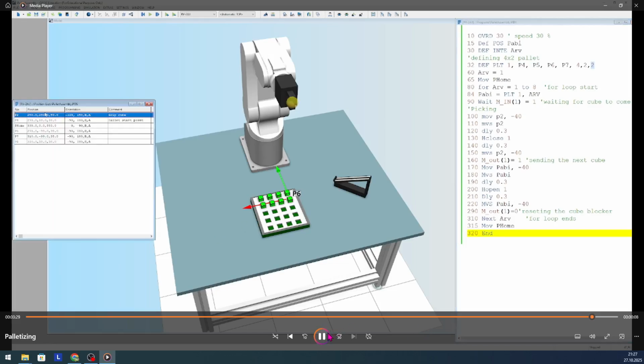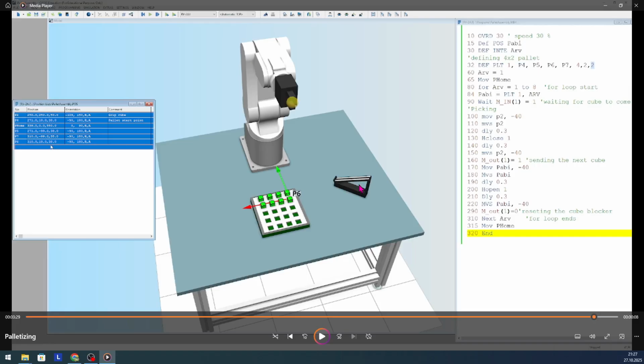So that's it. And one more thing about this that I would say, you see there's 2 windows here. One window is for the program. Mitsubishi has this system that all the programs of the Mitsubishi are saved in 2 different files. Like in Robot Studio was only 1 file. Here is 2 files. One is for program and one is for position, and I have to save both of them. And when I want to download to the robot, I have to download both of them separately, but with the same name exactly. Okay, that's all that I wanted to show.